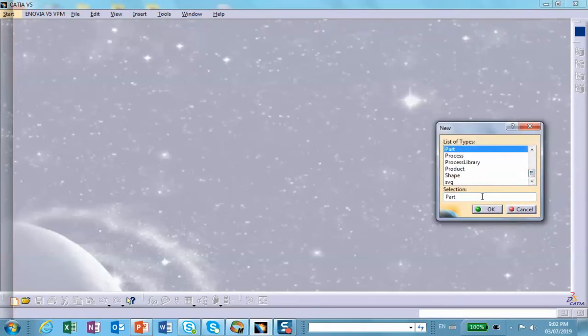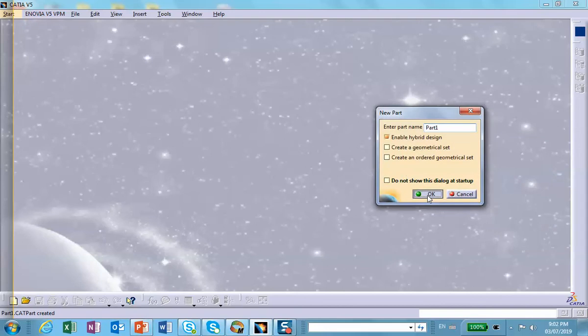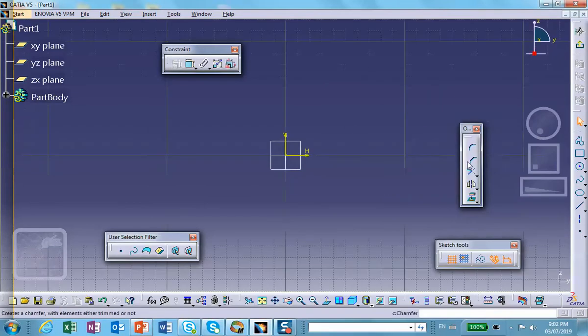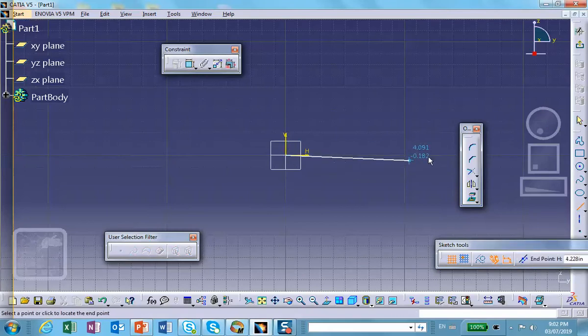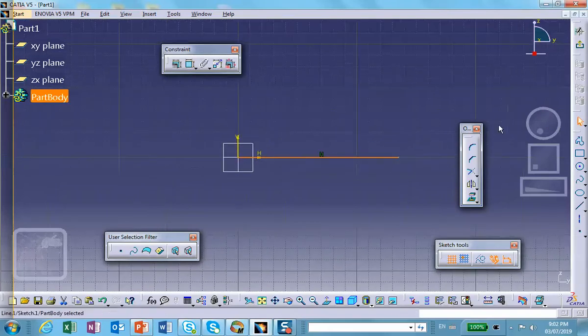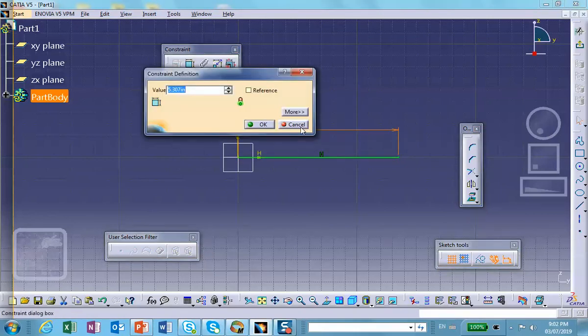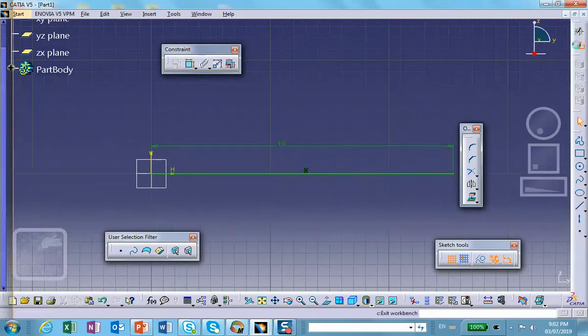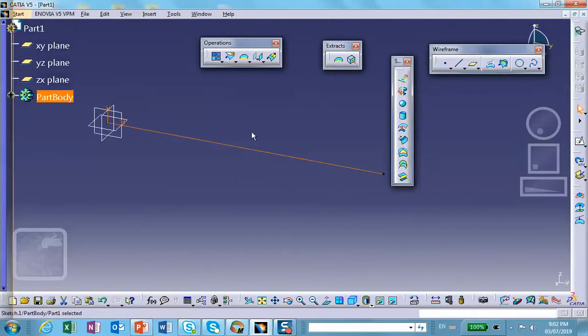Right there. Okay. So I'm going to create a sketch once again. So on that vertical plane, I will draw a line 10 inches long this time. Right there. 10 inches long. Let's make that thing actually 10 inches. Good. Exit. And join it.